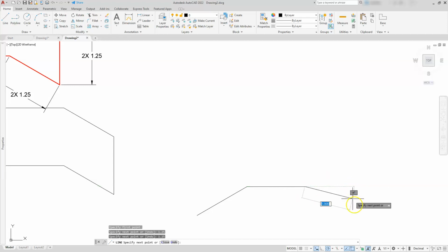I want to go down this direction, so I'm going here and I'm just rotating down, and you're going to see it's going to lock at 30 degrees. 1.25, enter. So you can already see the difference between using these two. One is that I'm going to have to physically look on the screen and see what's happening. And the other one, if I know the syntax, I can type it in without looking at the screen. So I'm going straight up and down in a vertical.